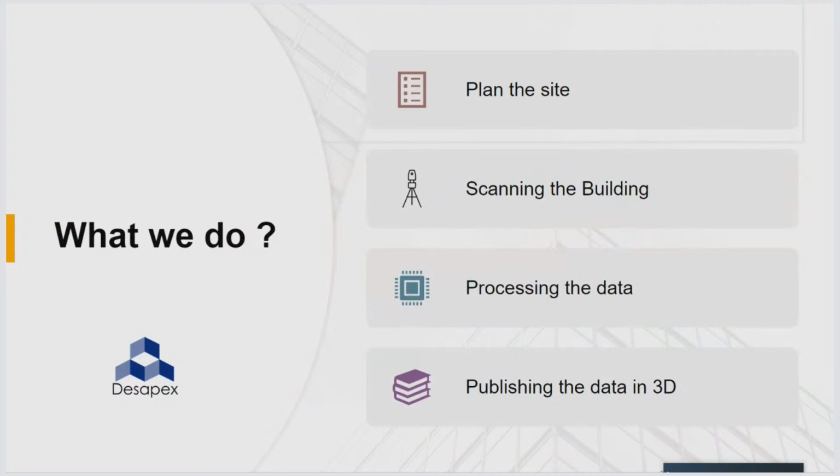So coming to laser scanning. Laser scanning is a non-contact, non-destructive technology that digitally captures the shape of a physical object using a line of laser light. The scanner emits laser beams, which hit the objects or all the elements available within the building. Once it bounces back, it records it as a scan point, so it creates a cloud of points. When we keep positioning the scanner in different locations, it captures a cloud of points, and it can be used to develop a 3D model.